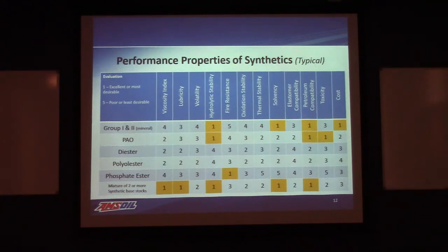Synthetics, generally speaking, across the board, tend to perform at a higher level than their mineral oil counterparts. And in some cases, to make a better product, you'll see synthetics that contain more than one base material, combinations, depending on the needs of the application.